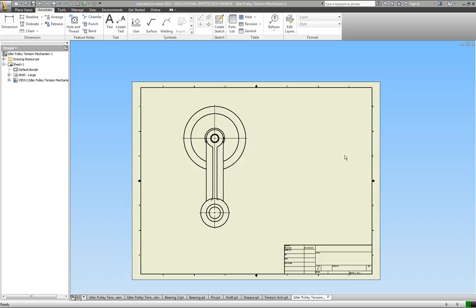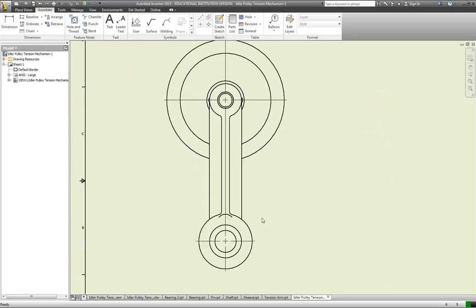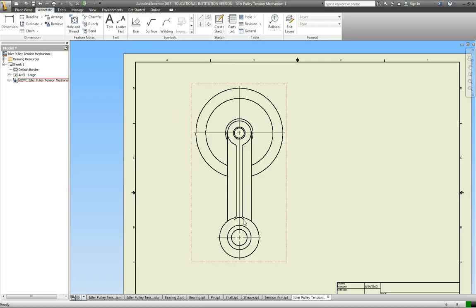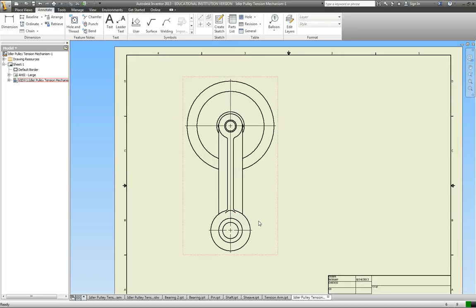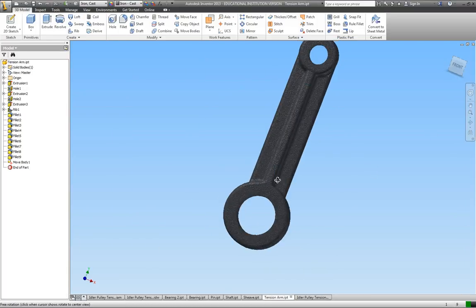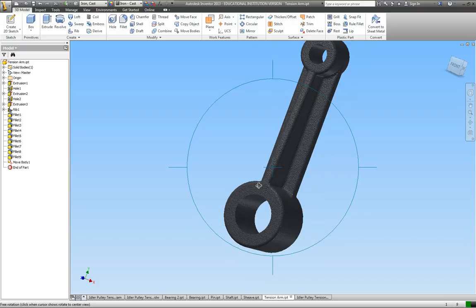So first thing I want to point out on my drawing, it may not be on yours, but I have this strange looking art thing that showed up on my view. Occasionally when you're doing fillets, especially complex fillets where you have three different surfaces meeting, you'll end up with some strange edges that will project into your layout from time to time. And while I was in my part drawing, I didn't even notice it. It's right here. That's what's showing up on the detail sheet.